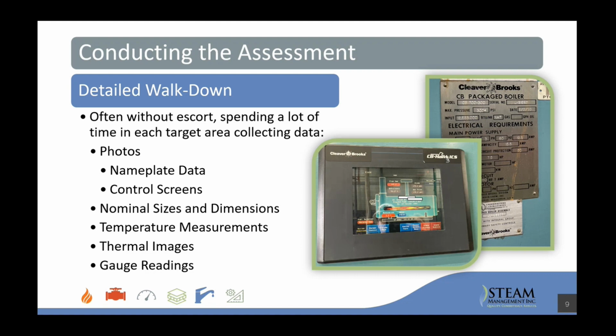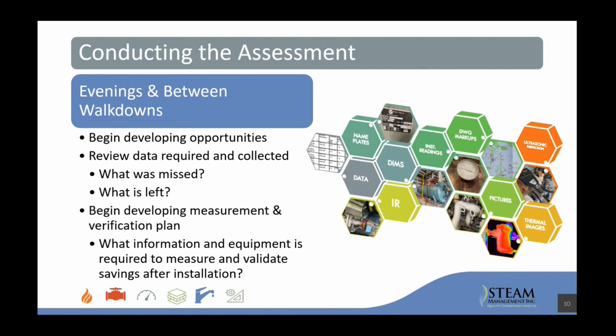I love to take a P&ID, like I said, and as you're making sense of the system and walking down the piping and identifying gauges, I like to write down what they read on the P&ID. So really, you're just getting all the data you can.